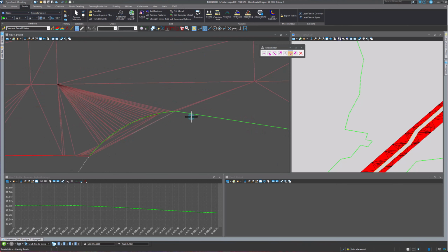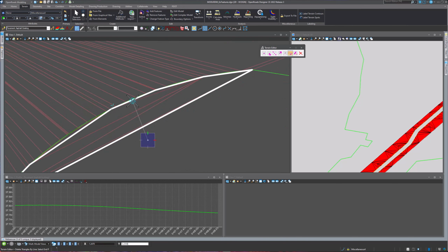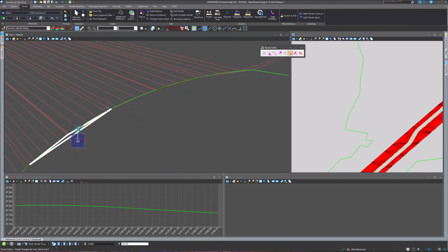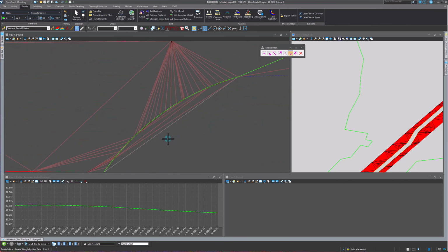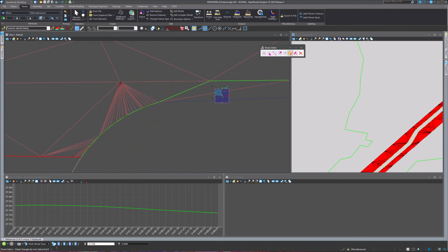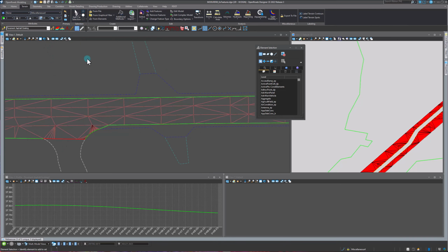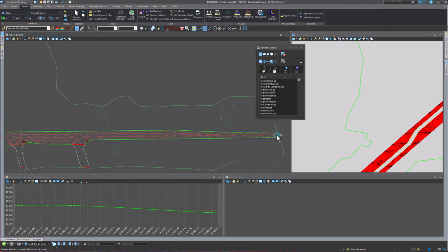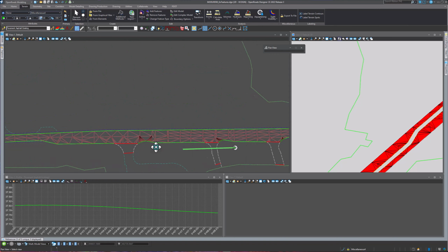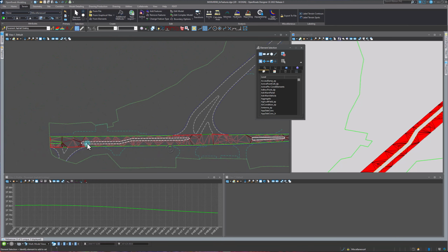So we'll just do this again, edit this. We'll draw lines there, there. And then I'm going to be daring here and get rid of these as well. And this one right here. And then Control S for save. Save often, just in case something happens and it crashes, especially when you're editing that terrain model. But now you can see I've got a nice clean terrain model there. Nothing's flying out. I've got the holes made.